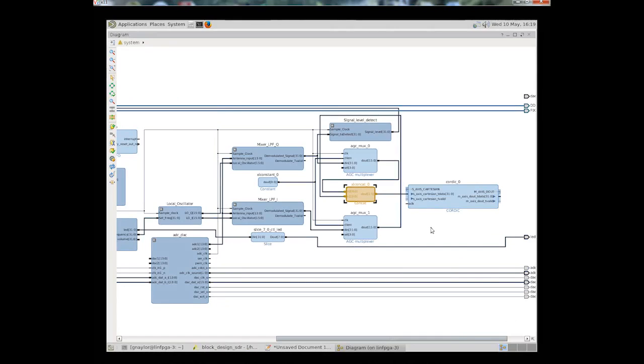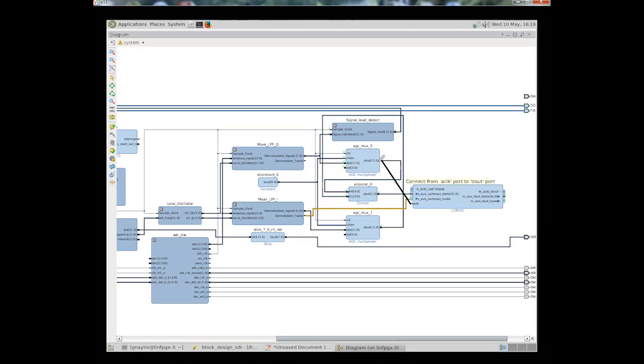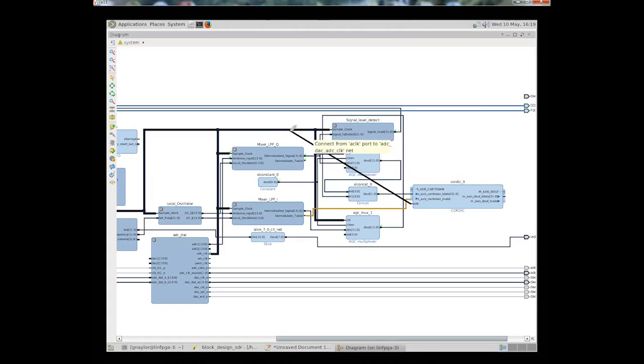T-valid, that's going to come from this rate here. So if you remember, this is our 32 kilohertz signal. So we'll use that to clock the codec. Either of these would do, they're both at the same rate. And the clock, again, will be our sample clock.